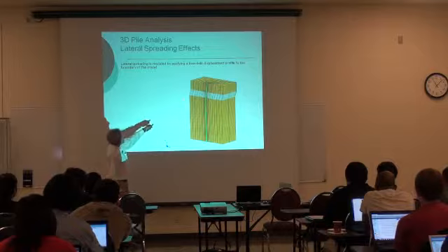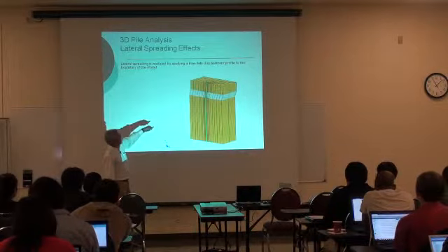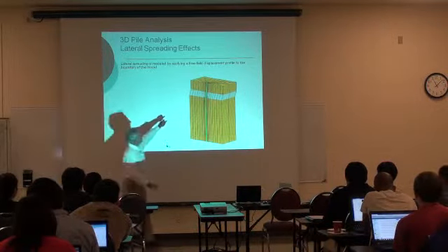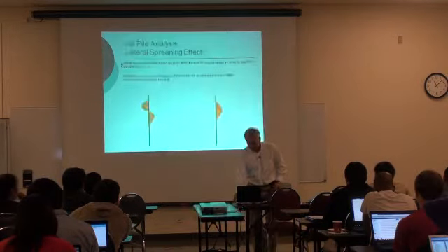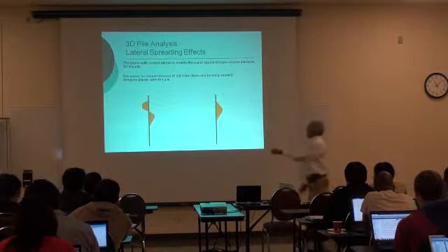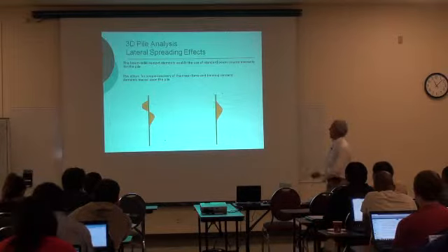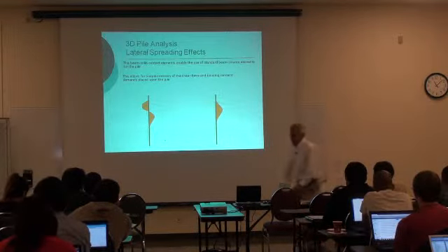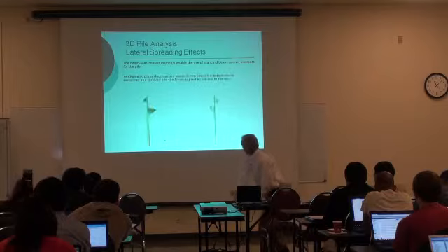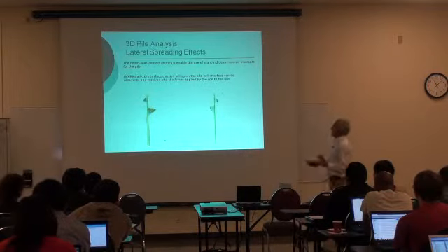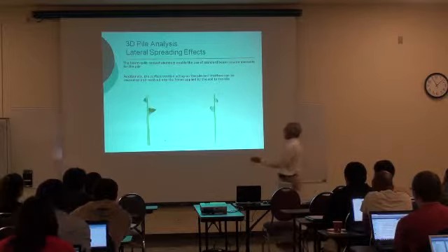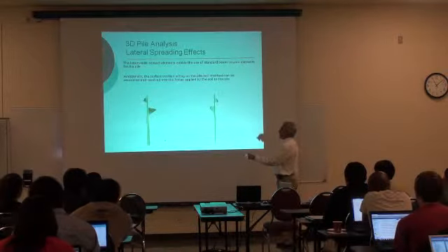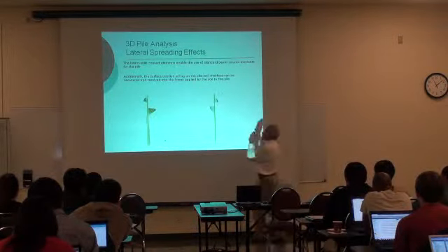By doing that, this mass of soil will impose a load on the pile, and then you can get the demands in terms of shears and moments. You can get the shear demand, and also the bending demand there. You can also start getting other things like the contact forces. Oh, this is interesting because I can get the contact forces around the pile or in one particular direction.